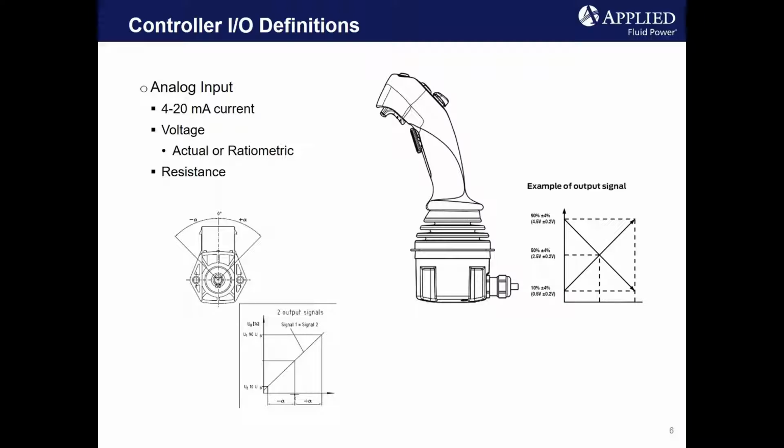Analog inputs can vary in range. Example devices that would send an analog voltage signal are joysticks, angle sensors, foot pedals, transducers, etc. Most analog voltage signals are sent in the range of 0.5 volt to 4.5 volts DC, which allows for detecting whether the device is working or not. If the device is not powered on or is malfunctioning, the signal will most likely be 0 volts.